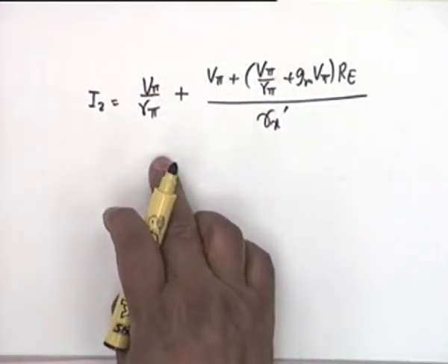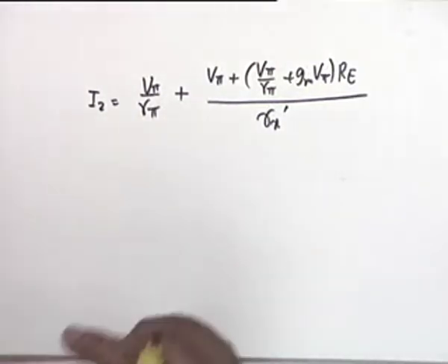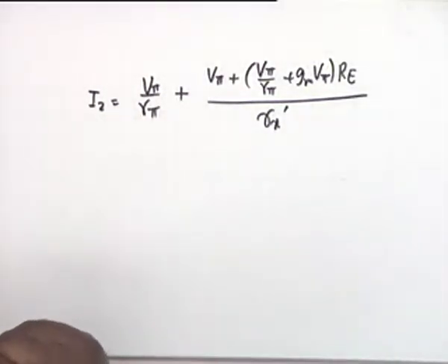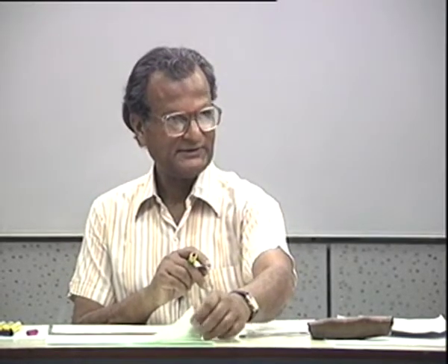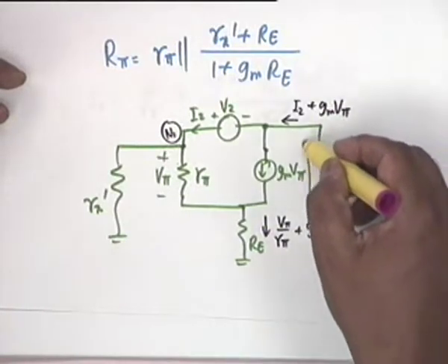Now in this equation I don't have V2, so I must write another equation involving V2. Alright, and that equation you have a choice. By choice you may also repeat the same equation. Don't do that choice, okay? Somehow you must involve V2, and therefore the easiest thing to do is to write a KVL around this loop.